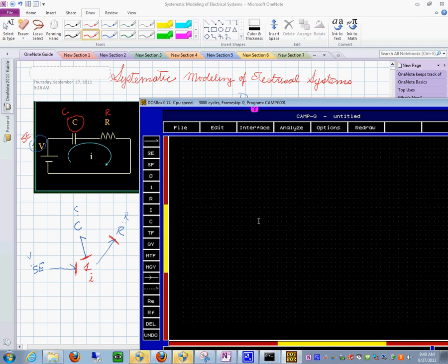See, what we're doing right now is the bond graph on the left hand side needs to be entered on CAMP-G. So you go in here and say, okay, this is an AC over there, right there. I'm going to place it on the screen, and then we need a one junction over here. So we're just drawing it, and the way you do it is you pick an element and you pick a junction, and you say from here to here, and the computer immediately uses that to assign a number to that connection, but also puts the power flow and the causal stroke immediately.